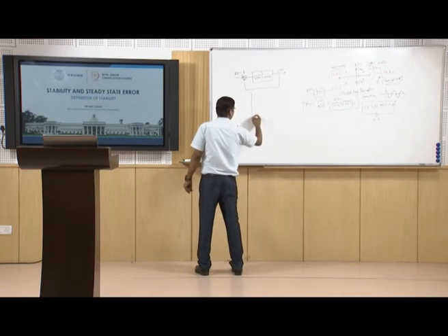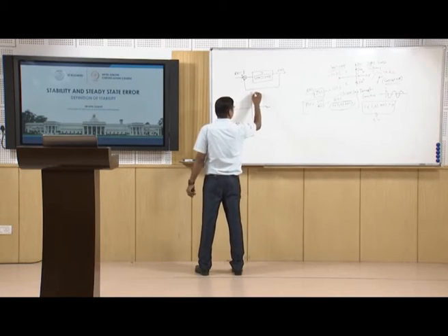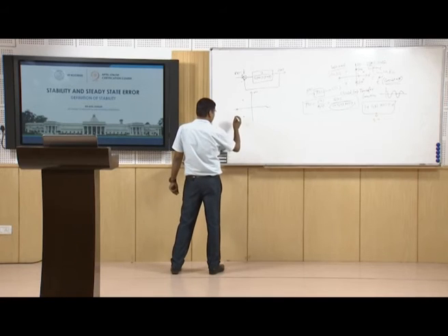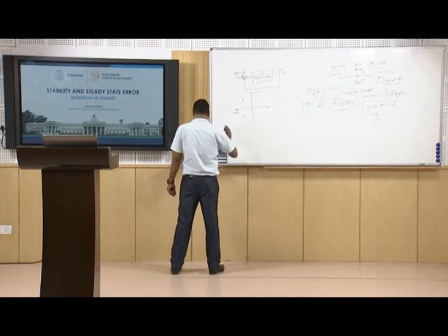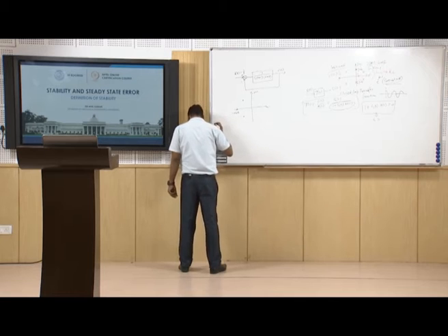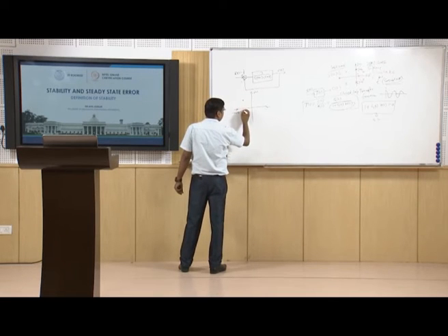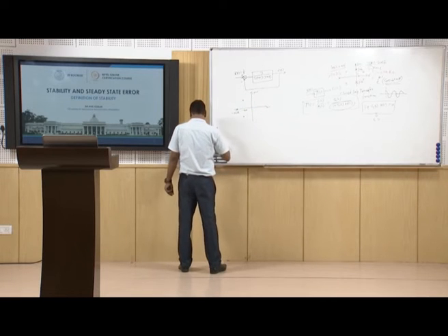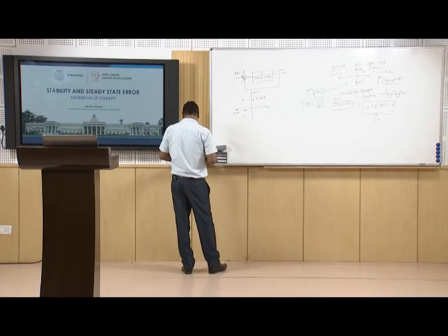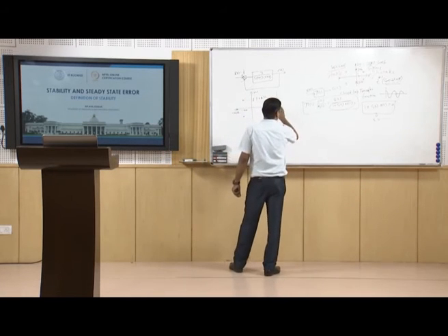When we find the poles, we will see that on this axis the poles lie in the left half plane, and this is minus 2.672, and this is 0.164, and this is j 1.047, and this is minus j 1.047, and we can see the response of the system with time